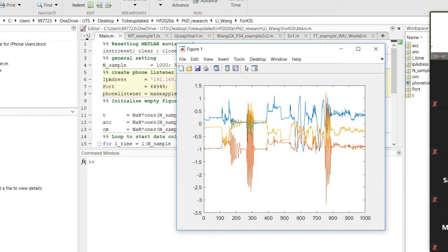But for IMU, after alignment, if we use GPS information, we can align with GPS first. Because GPS normally updates quite slowly, maybe 1 hertz, that means one update per second, in between we can use IMU to estimate all the information, even the speed and the angular velocity. All of these things can be estimated. So IMU is so powerful, and why? What's the theory behind it?